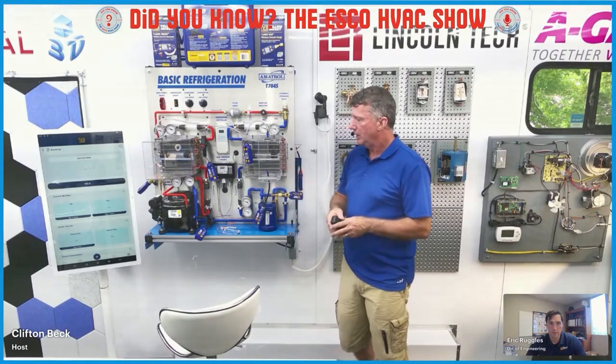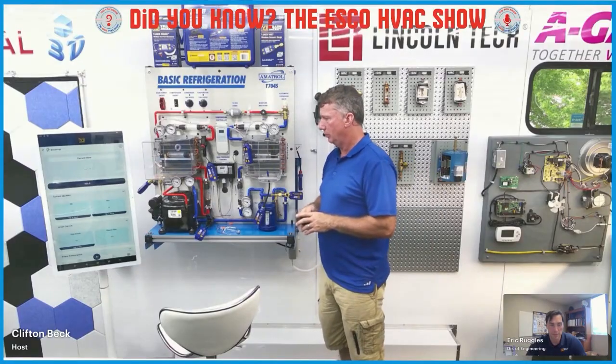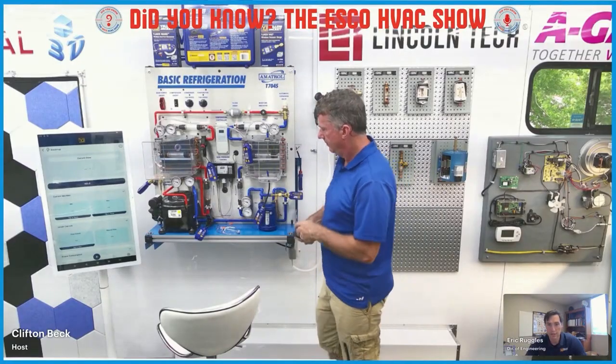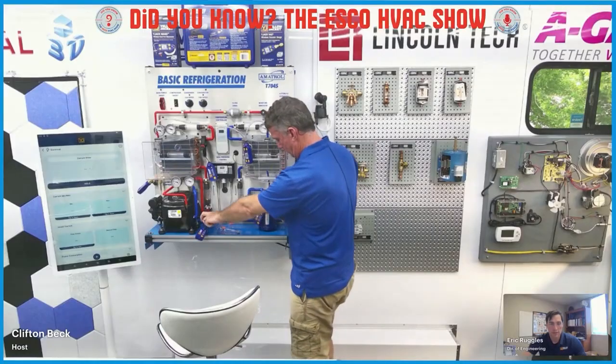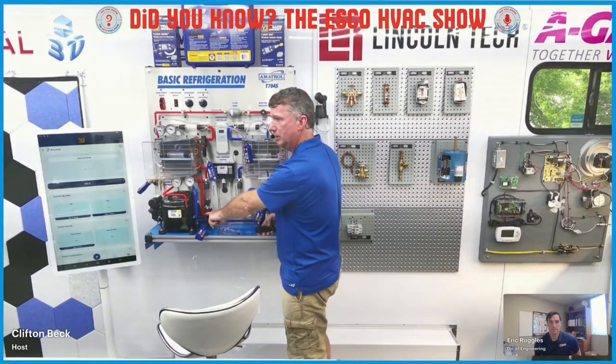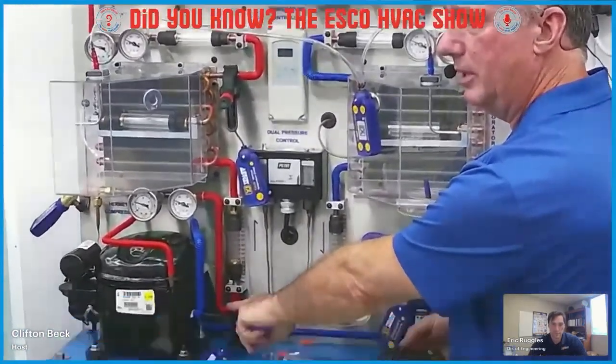Okay. So you have temperatures for the system side as well, right? So those are pipe clamps. Yep. And then again, you're going to need to put it on the low side and the high side, similar to your pressure locations. So here's our low side. Let me see if I can zoom into that one a little bit better for you.